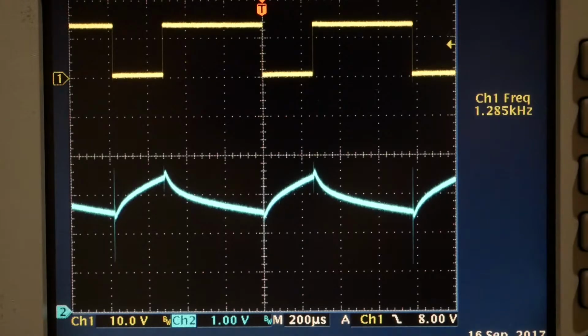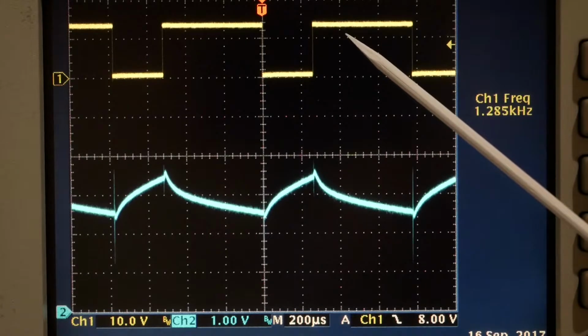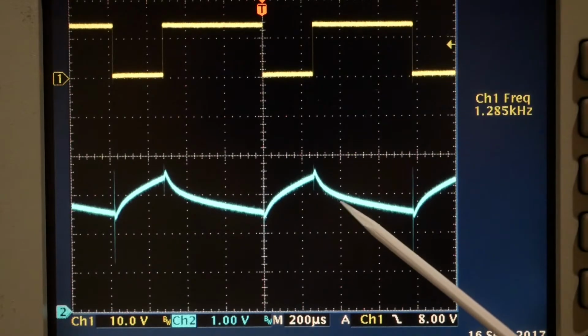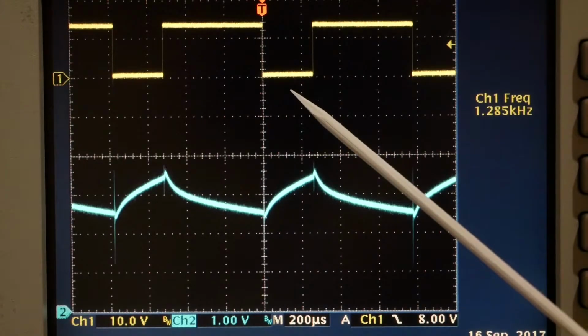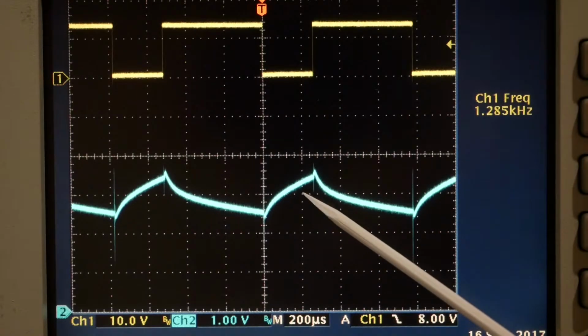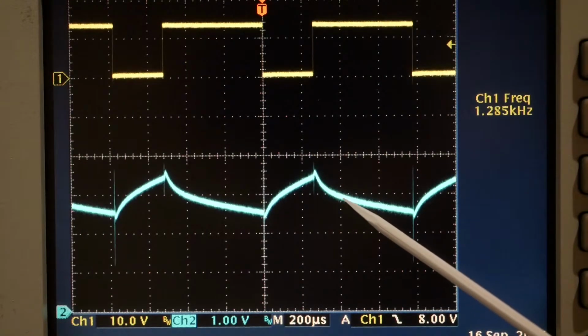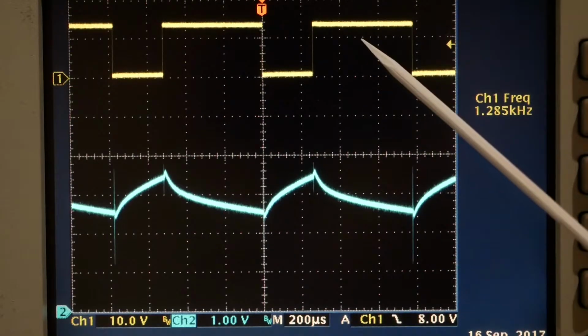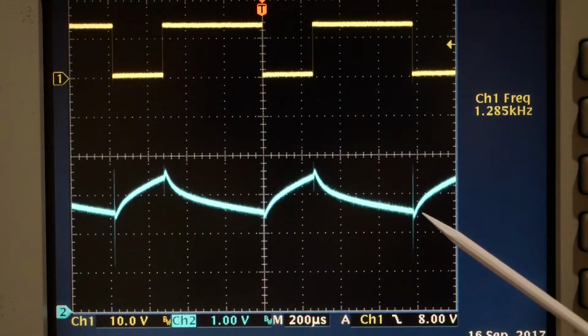In this first shot of the oscilloscope, the PWM voltage applied to the driven side of the solenoid is seen in the yellow trace, scope channel number 1. The resulting current flow in the solenoid appears in the blue trace of scope channel 2. Note that when the solenoid is momentarily turned on, denoted by the low voltage on channel 1, current begins to flow within the solenoid. Of course, it rises slowly because of the solenoid's inductance. Similarly, inductance keeps current flowing after the voltage drive is turned off, 12 volts here, and it drops gradually until the voltage across the solenoid is reapplied.